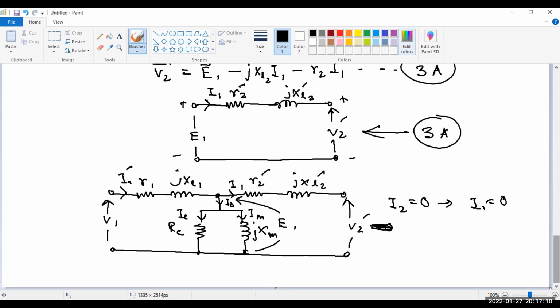Because if there are 1,000 transformers, now if we have 6 elements like this, you see here we have 6 elements, 3 resistances and 3 reactances. Now if we remove the shunt branch, then you will have only 1 resistance and 1 reactance. Your complexity of the problem will be reduced manifold. So therefore, in most cases, we go for an approximate equivalent circuit, not the exact equivalent circuit.